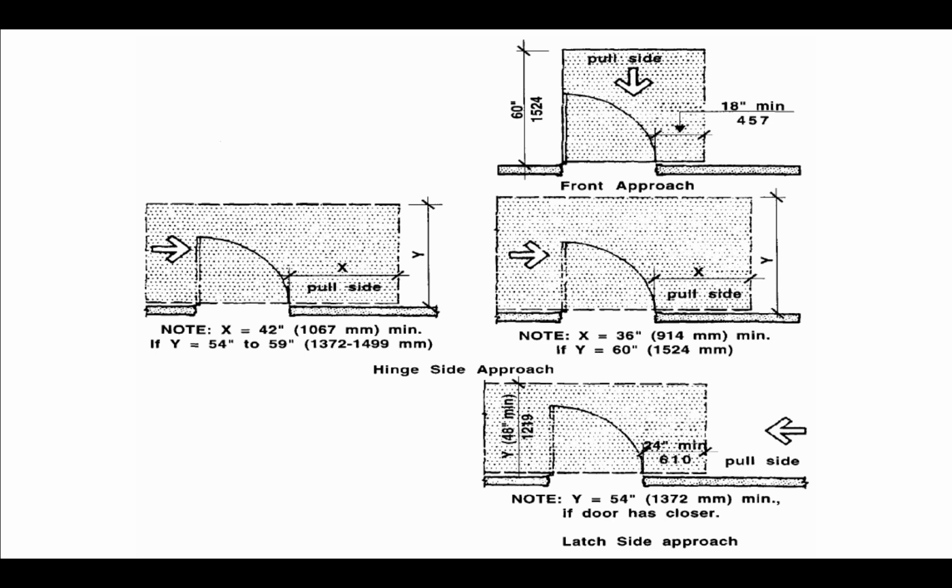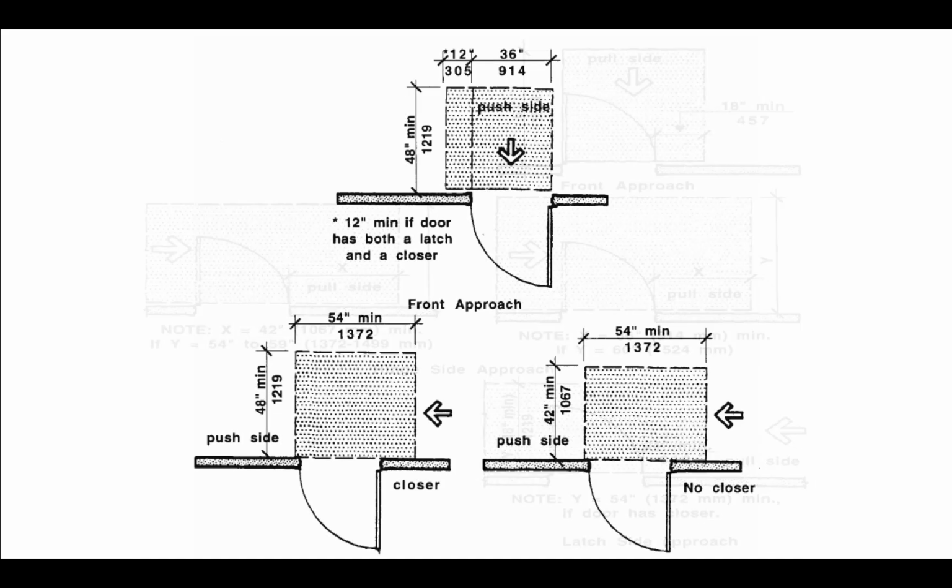It's just a matter of trying to remember that you have to have them. Infrequently, but sometimes you will run into trouble where the route that you approach a door from makes it so that you can't have clearance because there just isn't space. Typically places with lots of little offices. Anyway, for the most part, it depends on the direction you're coming at, if it's the push or pull side. So be sure you're vaguely aware of these clearances.